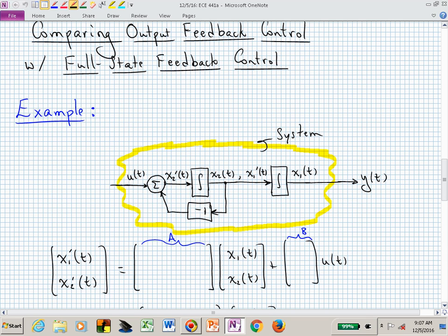then you assign those outputs of each integrator to be your state variables, which means I might have many different representations that are actually okay answers from the same problem. Because somebody might label the rightmost integrator's output x sub 1, somebody else might label it x sub 2, but you all, to get a correct result, would have how many state variables identified? Just 2. There's only 2 integrators. And the strategy is to assign the outputs of your integrators to be your state variables.